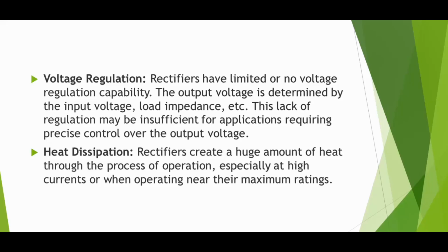The main advantage of rectifiers is its simple circuit and low cost. But its disadvantages are: the output current in the load contains, in addition to the DC component, an AC component of basic frequency equal to that of the input voltage frequency.